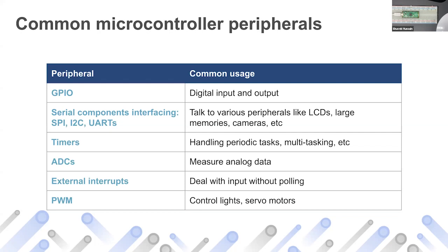It's very difficult to do using analog electronics, whereas using digital you can fairly easily do it, right? And of course, with PWM, you can also control the direction of servo motors. Servo motors are motors which don't rotate continuously. They can go to some direction. For example, you want to use it in robots or various driverless cars and stuff like that. You need to control the steering wheel. You need to say, turn the car 20 degrees or 15 degrees or whatever. You just hold the PWM pulse, and then you can control the servo motor very, very precisely, right? So PWMs are used for that.